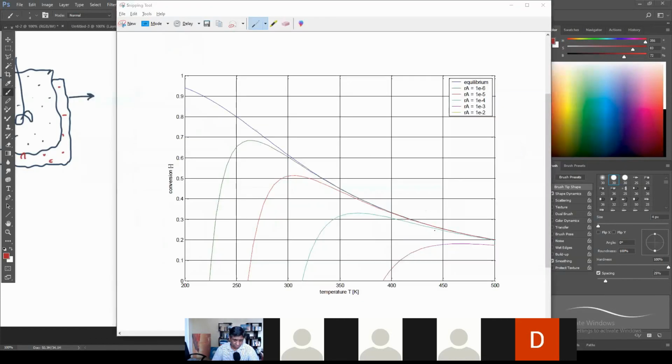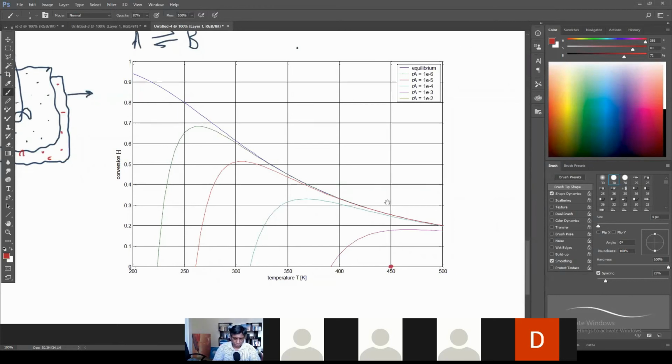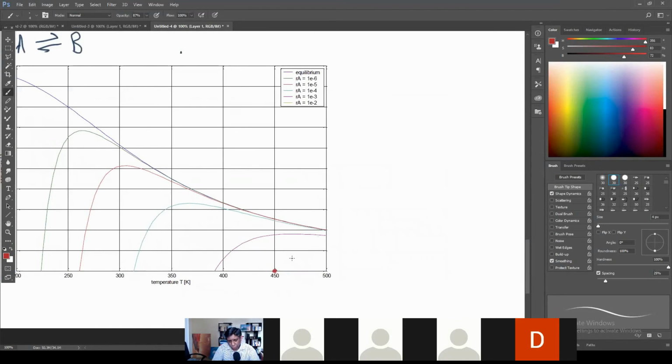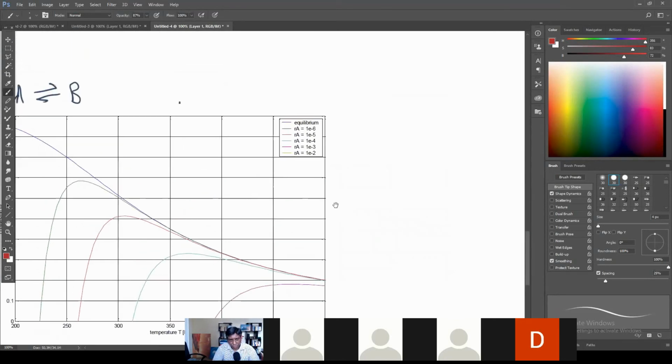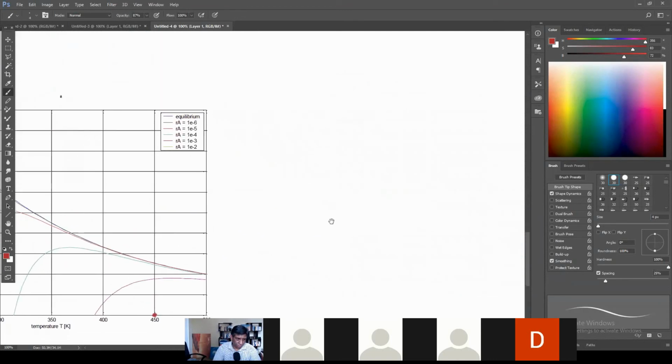And in fact, we know that there's going to be heating and all that applied. But before we implement heating and cooling, let's think about what the system will do initially. So we've got our reactor, and let's say we didn't have a jacket. What's going to happen in that reactor initially? We know that we have the adiabat available in that case.